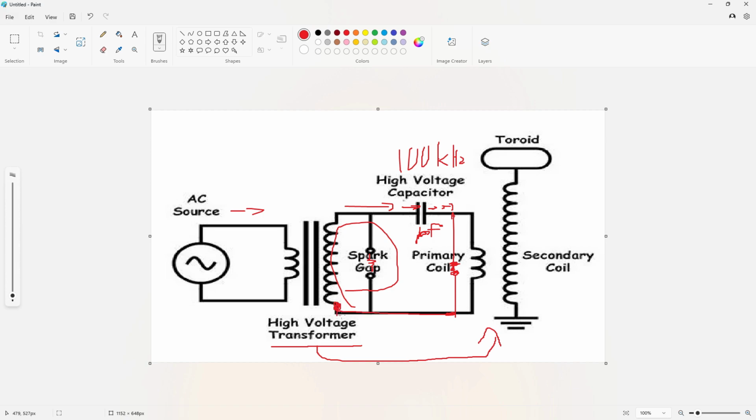Another thing I wanted to mention, because I don't know if it's clear, is that in AC circuits, when we're dealing with them inside of electronic circuitry or in schematics, there is no line or neutral. Line and neutral is something that comes from the house. You can't take your electrician knowledge, because some of it might screw up your electronics or electrical engineering knowledge in that respect, because line and neutral is a way things are wired in homes that has to do with safety reasons.